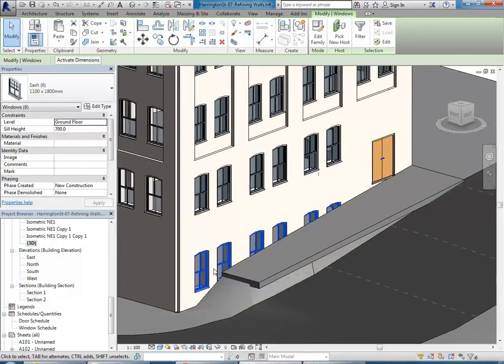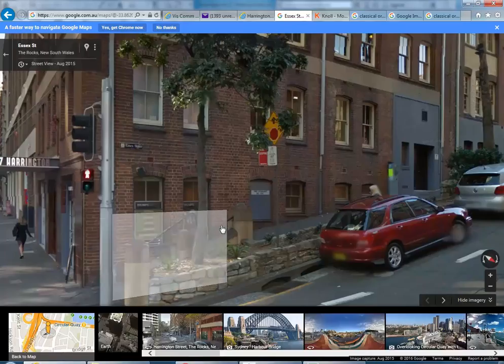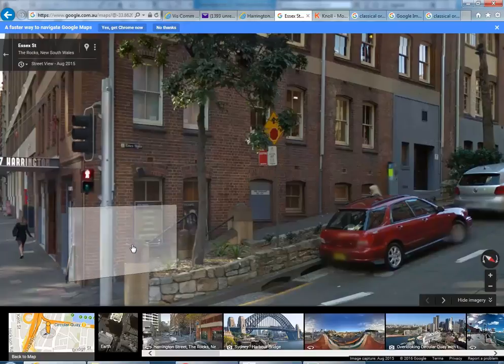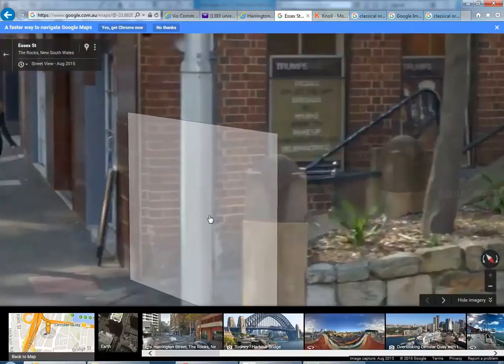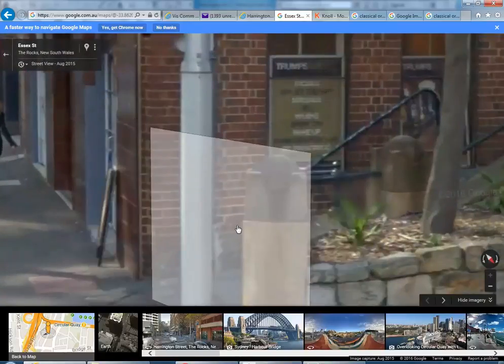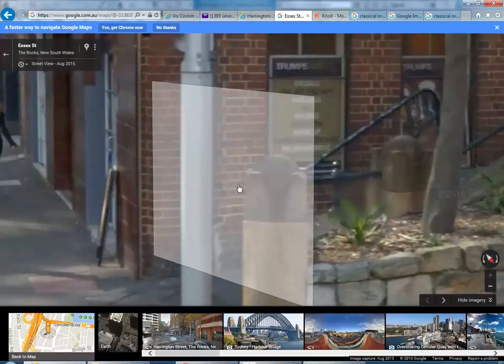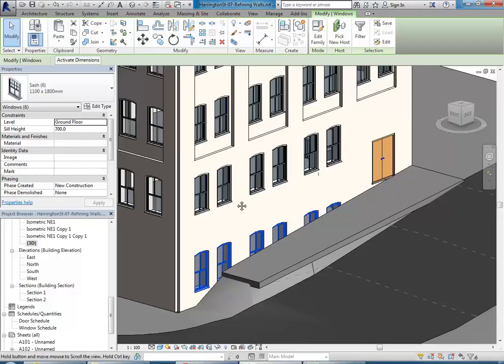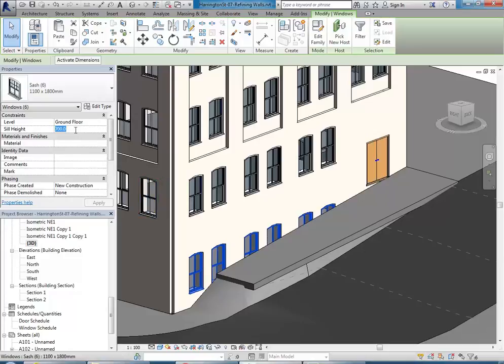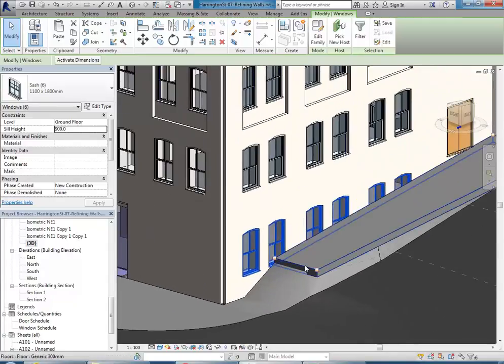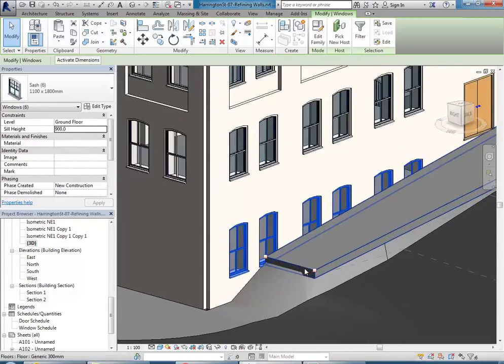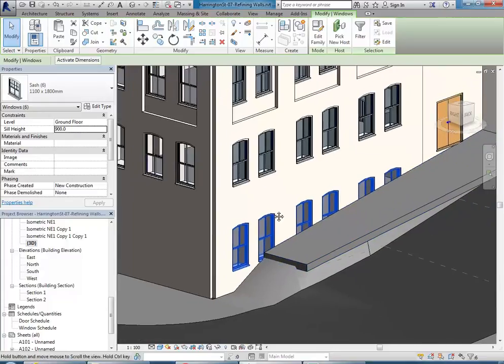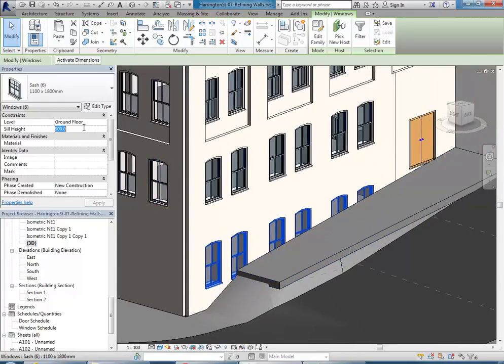So they're in the right location in plan, but the height needs to change. And so this is quite common actually. Ground floor windows are often higher. So you can see here actually we've got bricks we can count, which makes life easy. So 1, 2, 3, 7, 8, 9, 10 courses we'll say, which makes the sill height roughly 900. And then this floor level will probably come down slightly as well, possibly. But I might actually bring that a little bit higher, maybe 1,000.